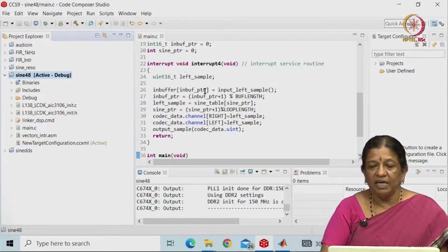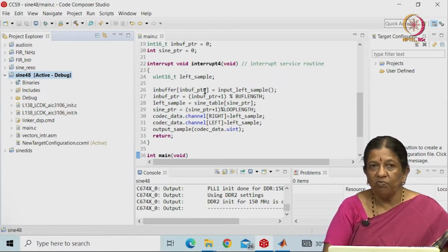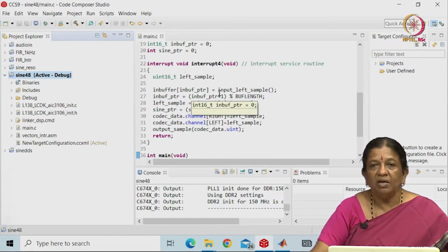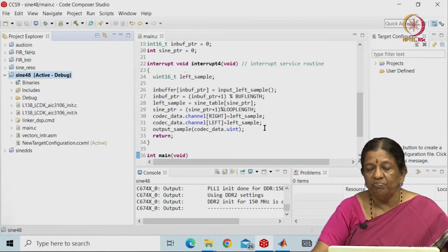Once I have taken the debugger and downloaded all my code into the board, it will be continuously running for whatever input you give it. This is what we call real time. Here we interrupt the CPU for every sample, collect the data into my buffer, and then take it out and play it.